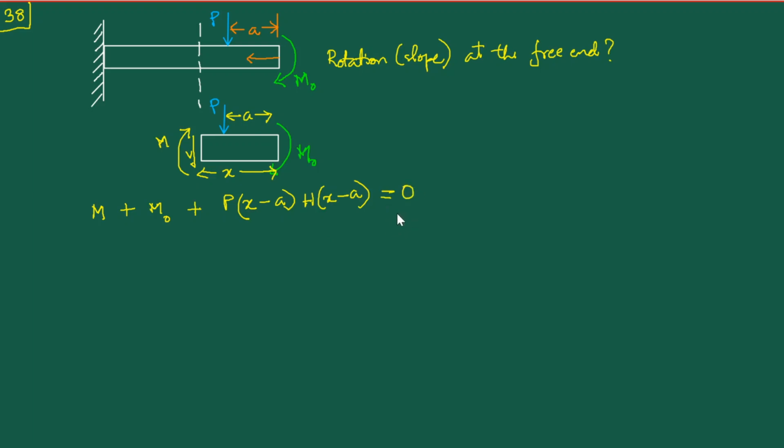Now yesterday, I have actually recorded the previous video yesterday, so I said yesterday, but in the previous video we had proceeded after writing something like this using the Macaulay bracket and then going to symbolic Python to do our calculations. But you see, for simple enough situations we can actually proceed by hand, which is what I'm going to show here. So just to make the thing nice and explicit, we write the actual expression for M, where this H is the Heaviside.